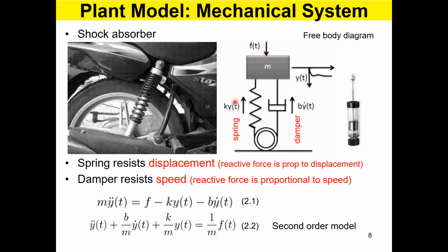If you look at the equations, how they produce the forces, you can clearly see their characteristics. Spring produces a force proportional to the deflection, how much the spring squeezes, or the deflection of the mass vertically downward. Damper produces a response based on the velocity. It's not a position-dependent force, it's a velocity-dependent force. If there's a velocity vertically downward, it produces a force. And the moment there's no velocity, there's no force from the damper.